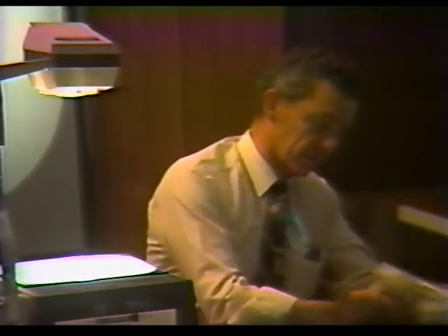Now, I've got a bunch of other stuff here that we could have talked about, but my time came out just about right, so I'm going to fill it out with one other thing that we worry about that fits in with what I've told you. In the case of bipolars, we generate all of these defects in the silicon that mess up our bipolars. Now, I did state that at room temperature, some of these defects do anneal out very quickly, in tens of milliseconds, for instance.